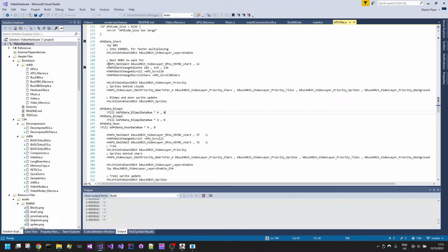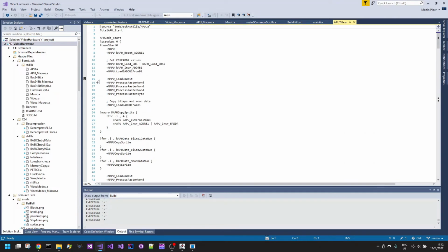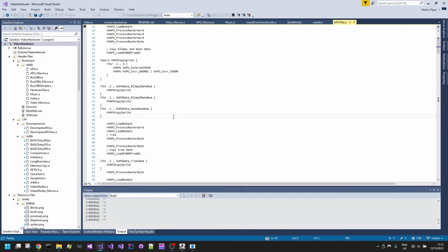But usually, because we want to optimize the whole process of copying memory internally to the video or audio hardware, we have the memory organized sequentially in the APU's data memory. And we have different information depending on what we're storing. We can store, for example, the scroll values, the characters, a palette change. So we need to make sure that the data layout is in synchronization with the code, so that the code is expecting to read the correct 16 bits of value or 3 bytes or whatever.